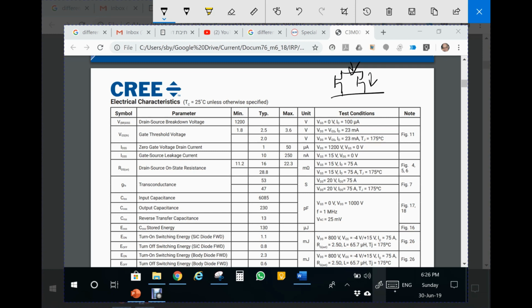Silicon, the change is much larger, which makes it better in this respect. It's worse in terms of the dissipation and the power loss, but in terms of current sharing, it's better. So the silicon carbide has a little bit of a problem sharing currents because when you take two units, of course, there is some spread of parameters, and it could be, you see, from this to this.